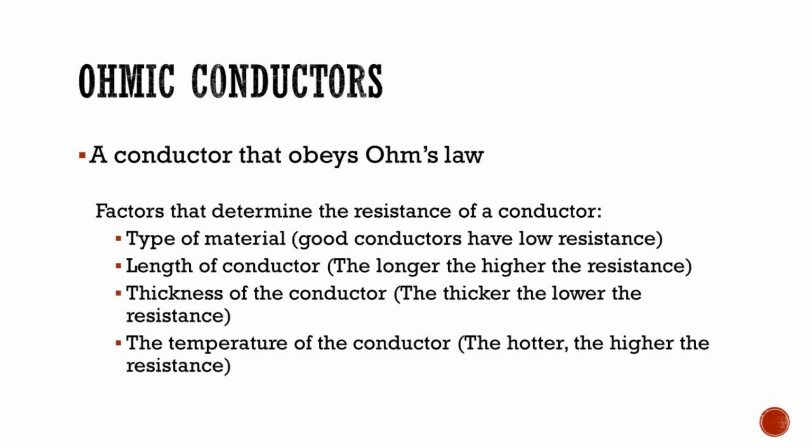Then the length of the conductor makes a difference in the resistance of the conductor. The longer the conductor, the higher the resistance. I don't know if you've ever noticed, perhaps with charging your phone, if you have a really, really long cable, your phone doesn't charge as effectively or as quickly. That is because that longer cable offers higher resistance, so it can't charge as well. So where extension cords are good, using too long extension cords can actually influence the resistance of the circuit and thus the functioning of the circuit.